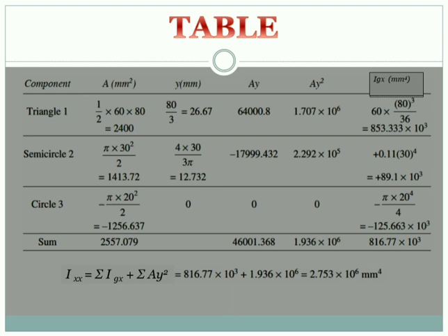Okay, so make a small correction while solving. One is that y2 is not taken with the negative value in the formula; take the negative value. Third is A3, which is the area of the circle, πr². So that divide by 2, you ignore it. So this is how we find the moment of inertia about the given axis.